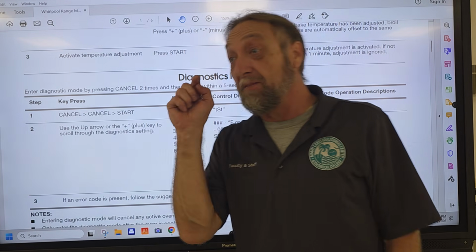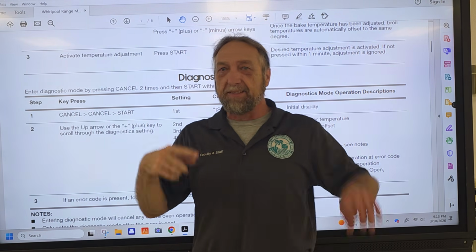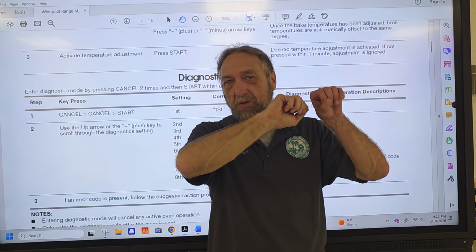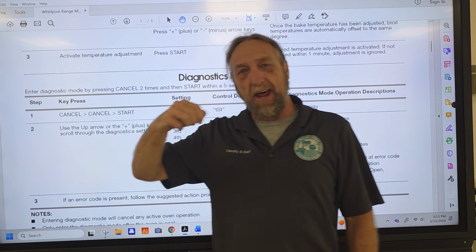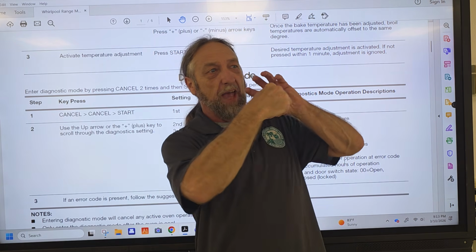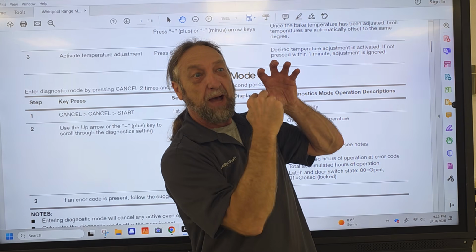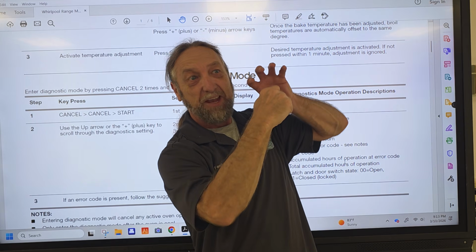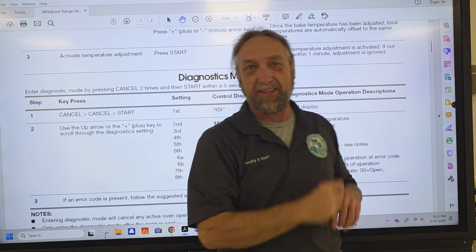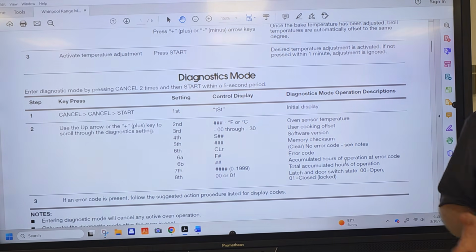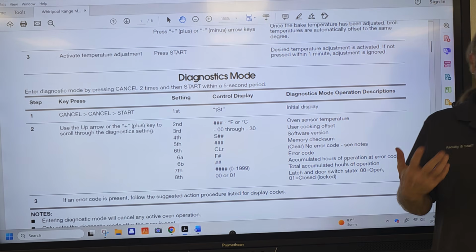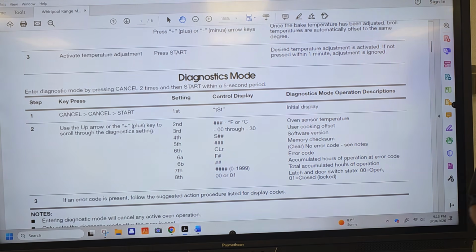Now, this is just in case you guys run into it. Instead of having a little screw down the shaft of the thermostat to adjust the oven temperature, they said, well, we're not gonna make the thermostat adjustable. We're gonna take the knob off, and on the back of the knob, there's 2 screws, and you can turn the back part of the knob that says 350 or 200, and you can turn it a little bit and line it back up and tighten it up so you adjust the knob and not the thermostat. But again, usually an adjustment requires a replacement, okay? But if it is off slightly, you know, it's under warranty and it's not a brand new unit, you can make a slight adjustment, the customer feels like you've taken care of that, all right?